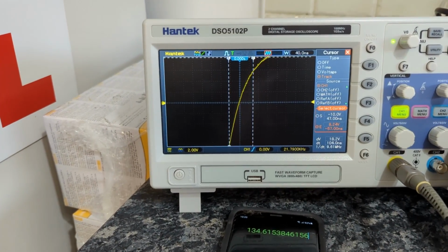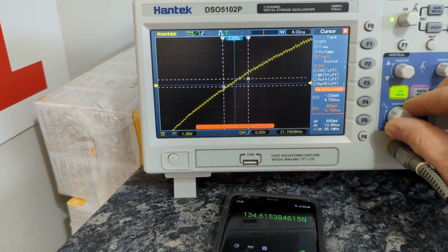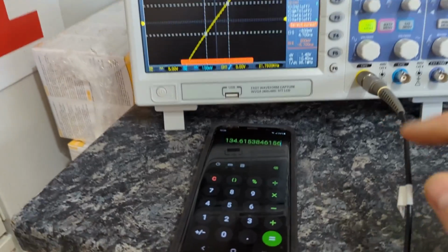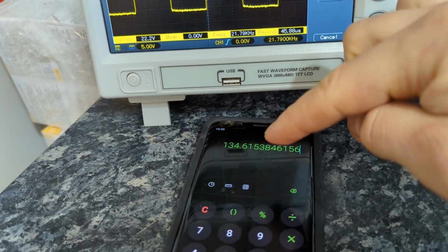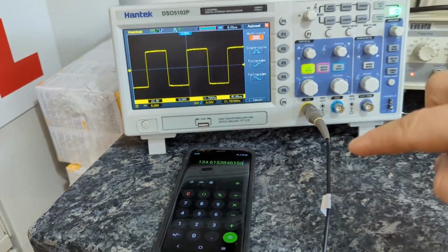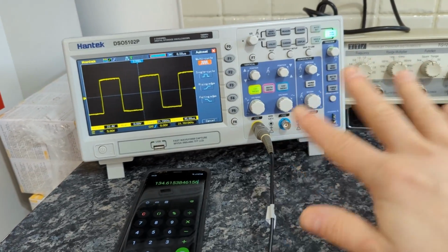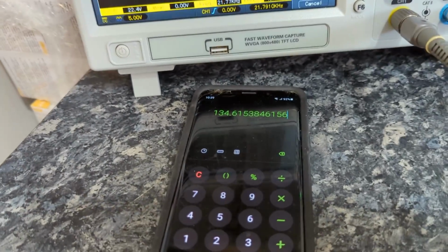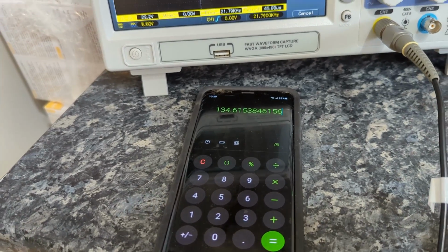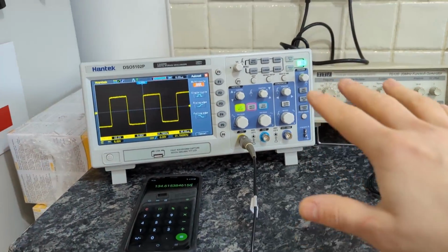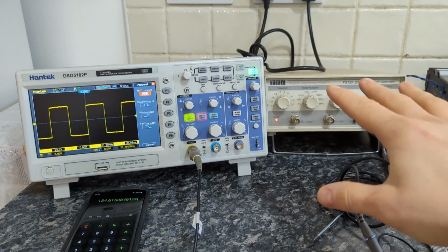So if I'm gonna measure an amplifier, obviously it's not gonna, but if the amplifier is gonna measure something close to 100 volts, 130 volts per microsecond, then I know that this is kind of a limitation of this thing and not the amplifier, but we're gonna see much lower numbers, I guarantee. So this was on the loopback, basically the scope measuring the generator.